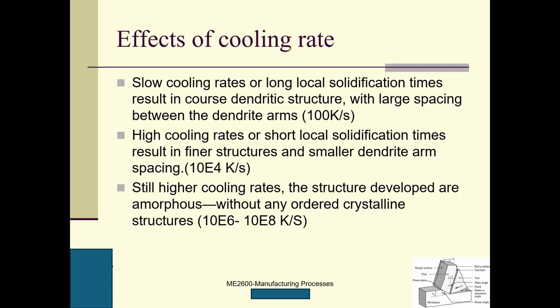If the cooling rate is very, very high, the metallic atoms do not have time to form any patterns, and then we will have an amorphous structure. Amorphous structure is also called glassy structure. Amorphous means that we don't have any obvious patterns.